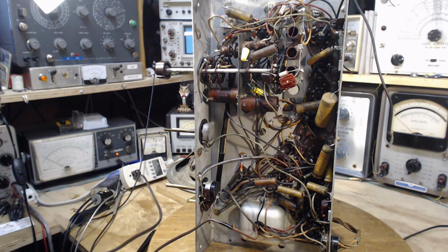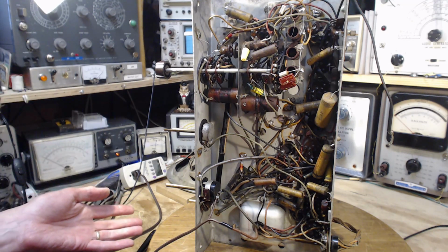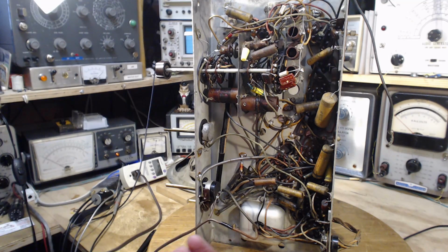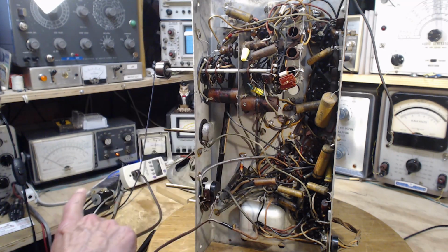So if the local oscillator is weak, there are two ways I know of to detect that, aside from hearing the radio not working. One is to measure the grid voltage on the oscillator grid of the mixer tube. That voltage should be negative, and the stronger the oscillator, the more negative it is. So I could potentially hook up my meter here, turn on a working band like the broadcast band, and see a value. The value itself doesn't matter, but then flip through the bands and see if that value stays about the same or if it drops off on the bad band. I left the power on to this radio. Shame on me.